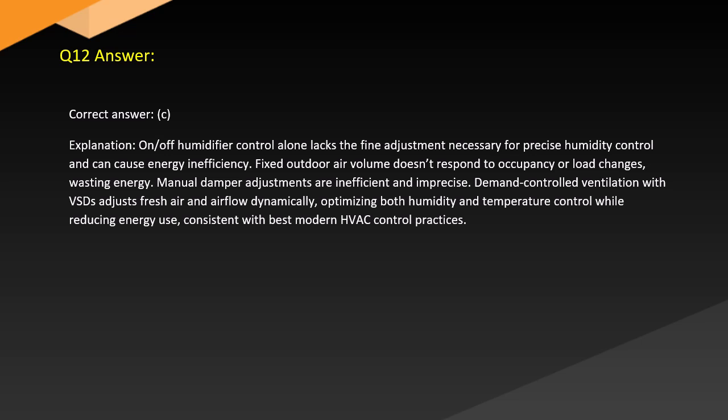Fixed outdoor air volume doesn't respond to occupancy or load changes, wasting energy. Manual damper adjustments are inefficient and imprecise. Demand-controlled ventilation with VSDs adjusts fresh air and airflow dynamically, optimizing both humidity and temperature control while reducing energy use, consistent with best modern HVAC control practices.